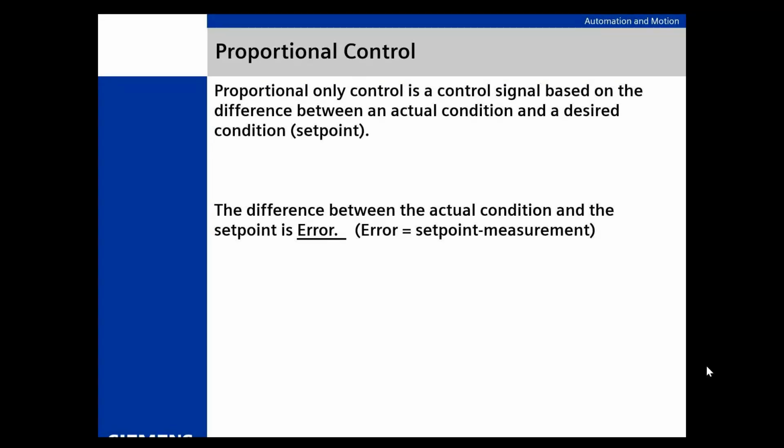Proportional control is good for what it's good for. You don't have to have all this complexity. In fact, in this illustration of your thermostat, tight control would be bad because that constant on-off would make your air conditioner come apart.